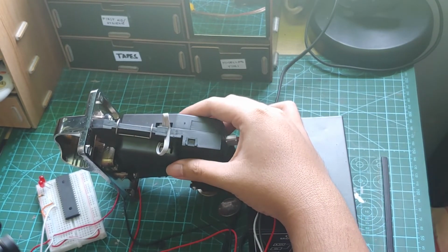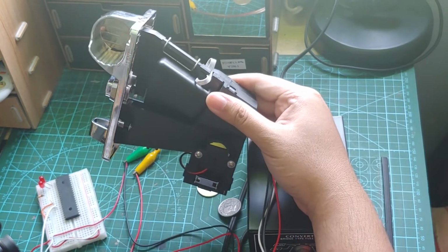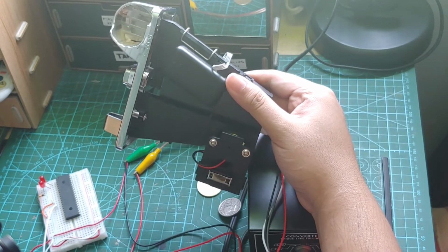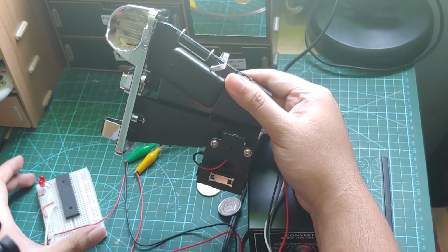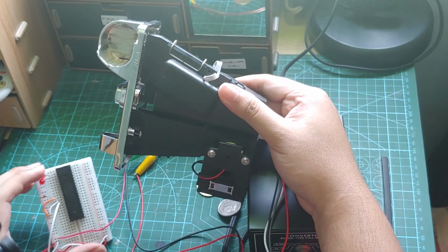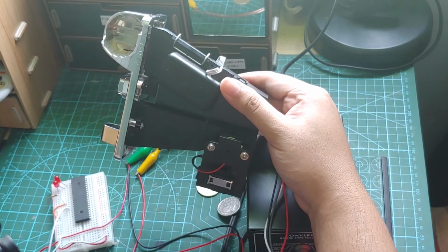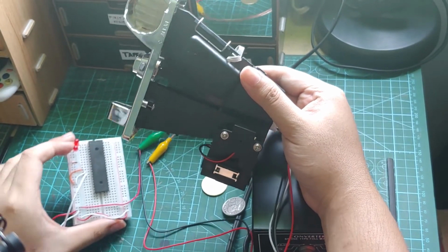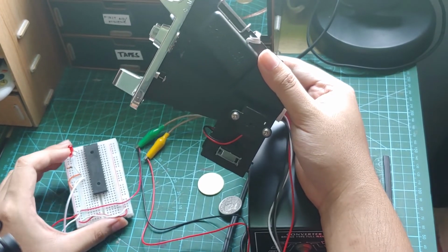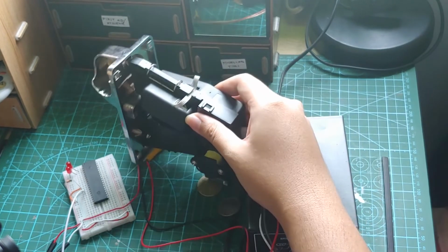So this is my project for DigiElex2 Lec that uses a coin acceptor. So it says that the LED at RB0 should light up for 3 seconds when a 1 peso coin is inserted, and the LED at RB1 should light up when a 5 peso coin is inserted for 6 seconds.